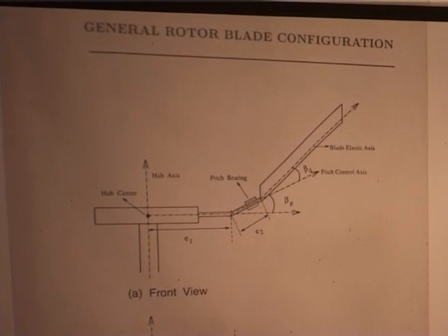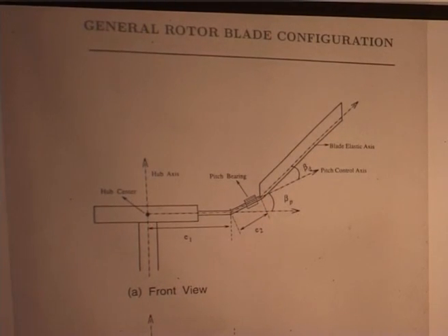In the equilibrium level, equilibrium is whatever we obtained as the loads, it reduces the root load, the root moment basically. But if you take the effect of that on stability, stability means not blade stability, but flap, lag, torsion.